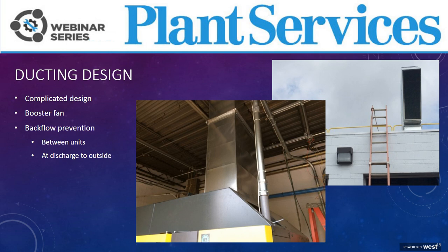The length that you're ducting to the ceiling or outside also needs to be considered in that overall pressure drop calculation. In addition, bird screens not only on the inlet but also at the discharge need to be considered. So inlet to the room and then discharge like you see there with the duct outside. Otherwise, you may have some unwanted guests in your compressor or your compressor room. Plus, if you don't have a gravity damper on the outside of your facility, warm or cold air can easily get back into your compressor, which can keep it from staying loaded or starting.